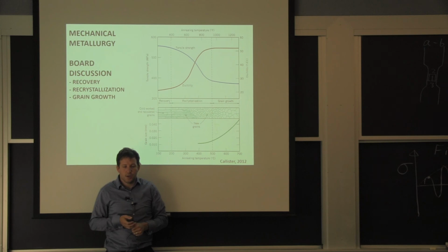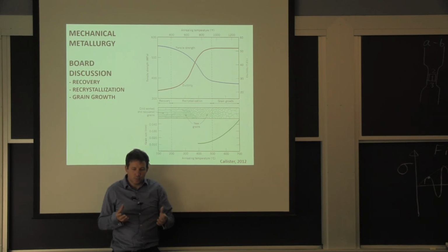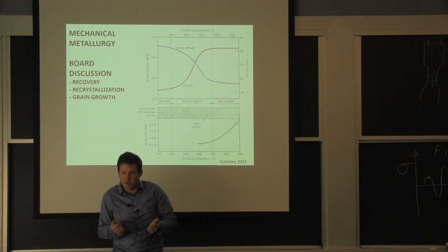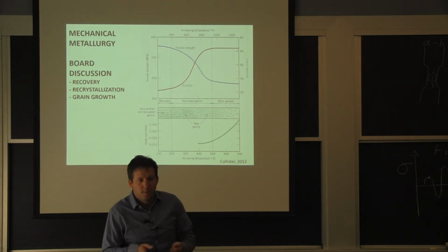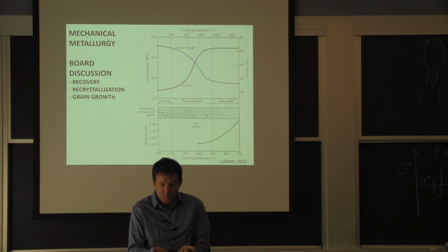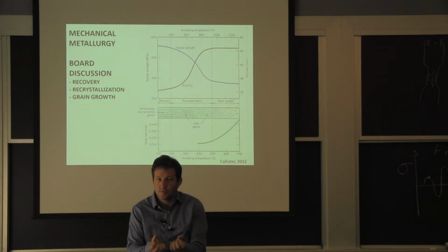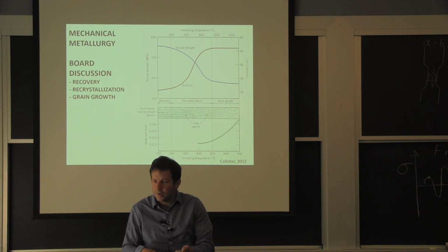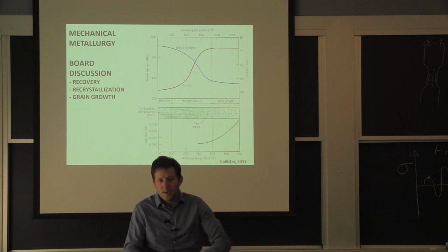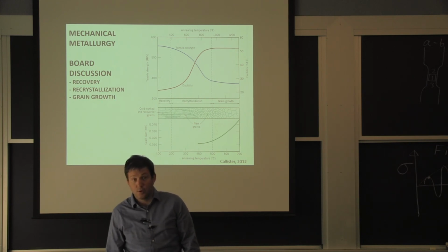We had a project where our client wanted to use pure aluminum for its ductility for medical devices, and they had tremendous problems because you deform it locally. Say you have a tube for a surgery operation, you deform it locally, and in that deformation zone, all of a sudden the grains grew very much. Aluminum is a low temperature alloy. The grains grow, and then you lose your ductility, you lose your strength. So when you try to bend it back, it's not good.